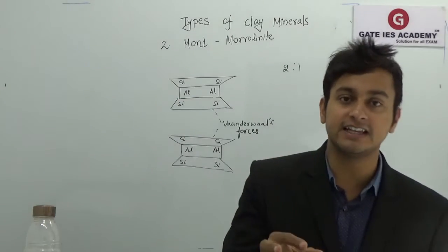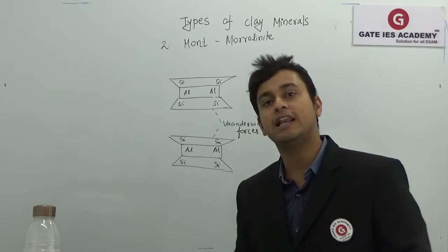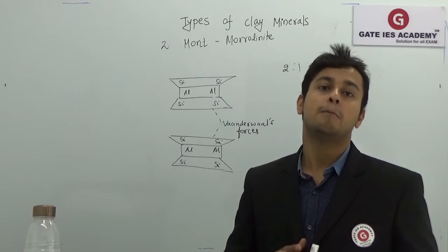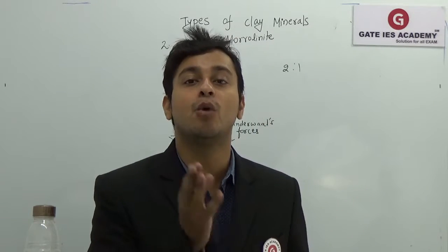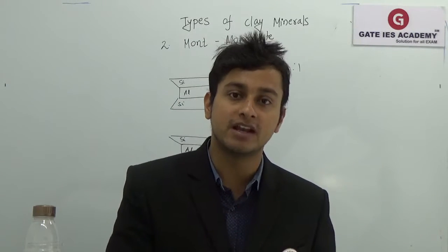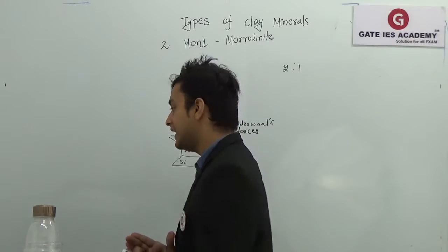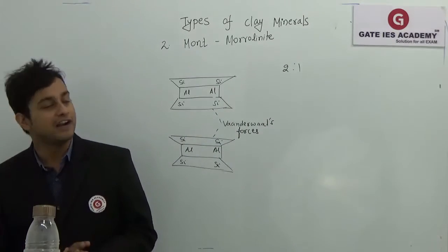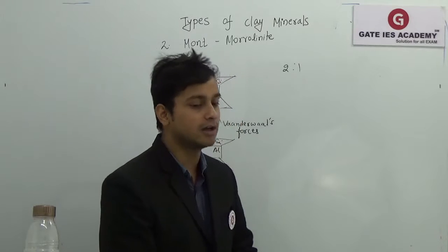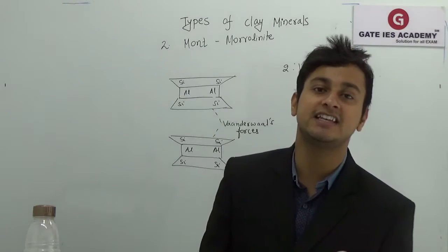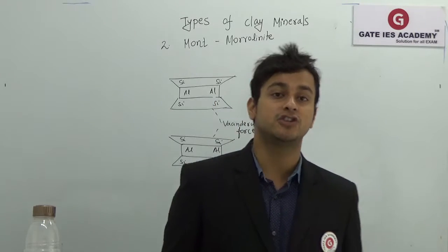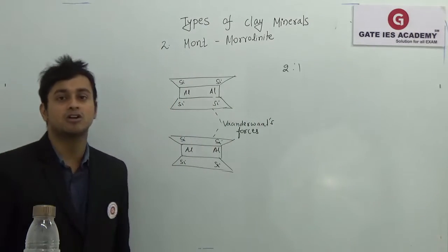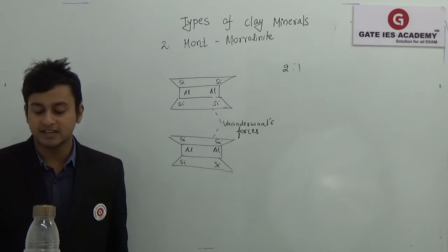Very easily the water will come in, and therefore it will swell or shrink the molecules, and therefore it is the highest or the most active mineral possible, because it has voids which are filled with water. It can take a lot of water because its bonds are very easily breakable. That is what the mineralogical composition of Montmorillonite is all about. Please write down.